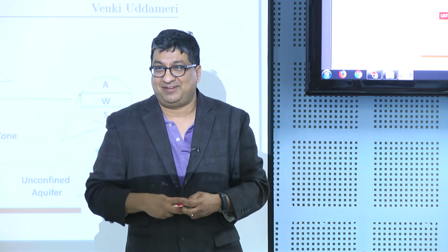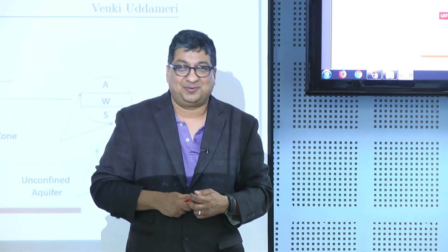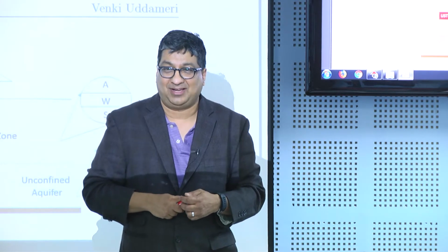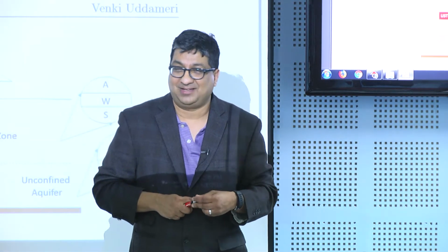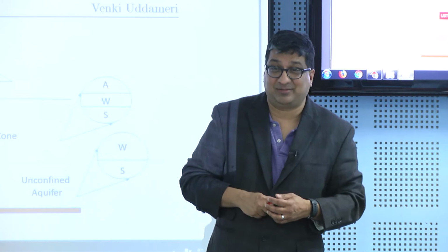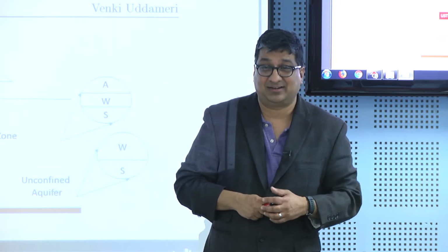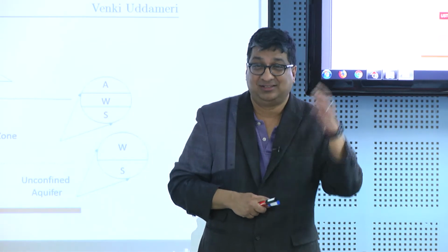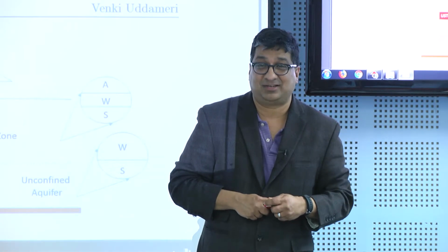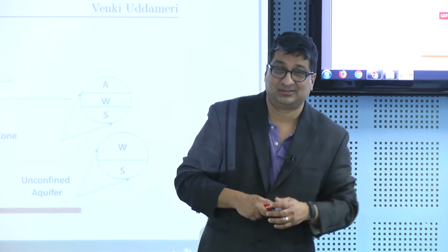If you have it in centimeters per year, it's probably in clay. You have a lot of clays. If it's in centimeters per day to almost tens of centimeters per day, you probably have nice sand and gravel. That's where you need to put your well. If it's centimeters per year, don't waste your time and money putting in a well. You will not get water, so it's not usually a worry.